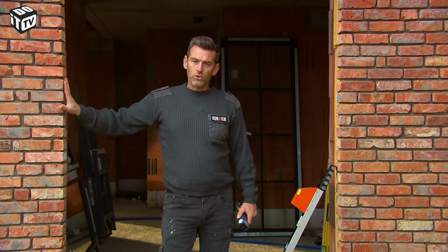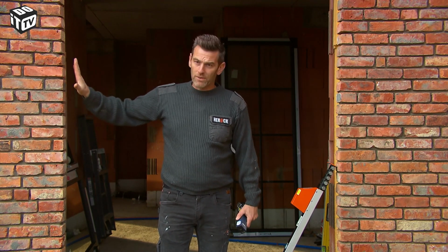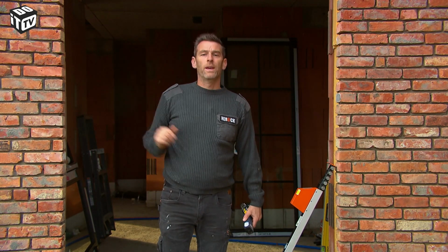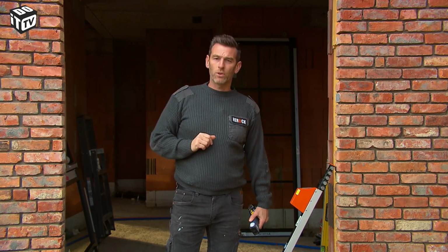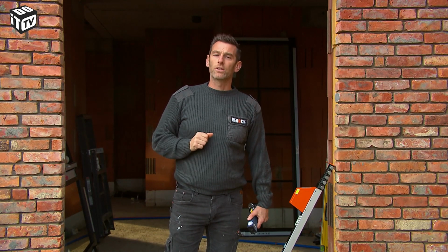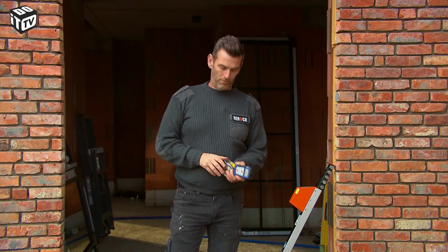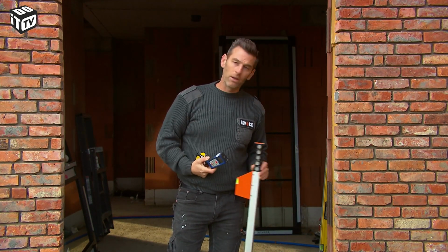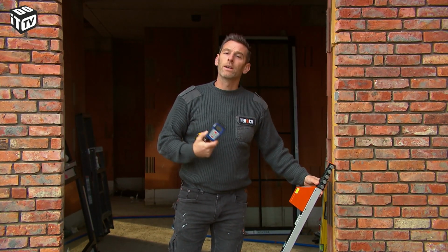We are now going to measure the window opening in the daylight size. This means between the facade bricks on the outside and between the threshold and the top. Here we'll add 2 cm left, right, and top. It's the production size to input into the system. We're going to measure with a tape, laser, or rod meter. You can also use this. It's simpler.